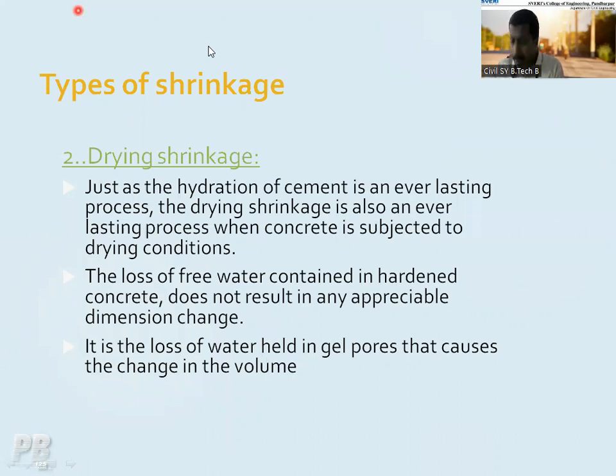Definitely. Okay. So that is nothing but the drying shrinkage. In drying shrinkage, there is a loss of water, definitely. But from which point is there a loss of water? There is a loss of water from the gel pores.